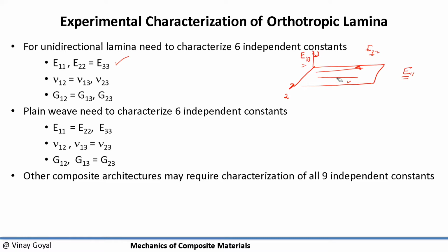Now when I look at nu 2,3, that's an interesting story, right? The fibers are going this way again. I'm applying a load in the two direction, and I measure the contraction in the third direction.